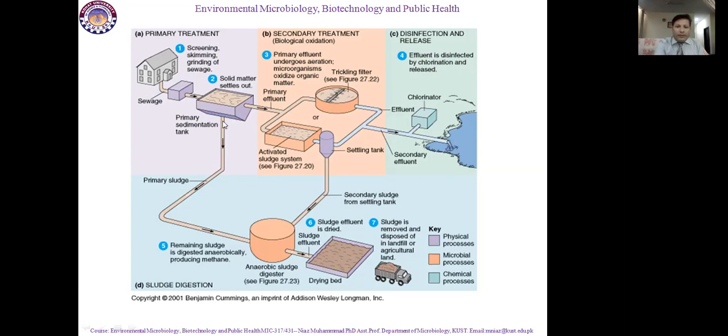But what happened with the material which was not soluble? It will move to the anaerobic digester. And from the digester tank, and from this also, undigested, undecomposed material will move towards this anaerobic digester. Here, anaerobic microorganisms will decompose all available organic material and resistant organic material, and gradually we move it to another place.